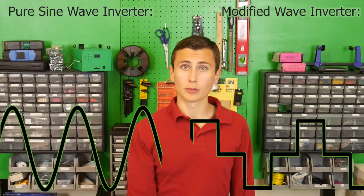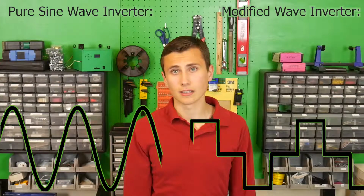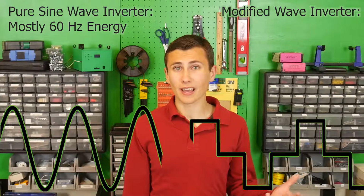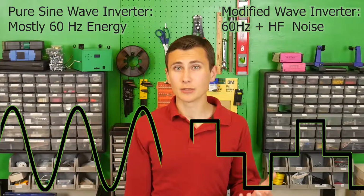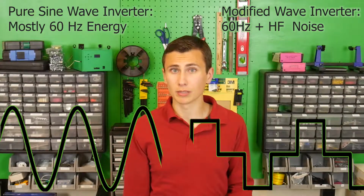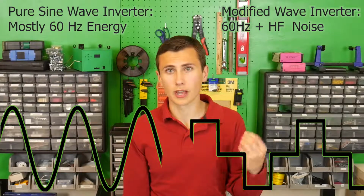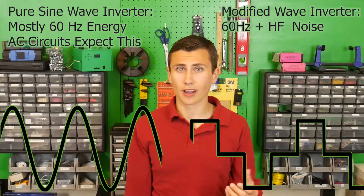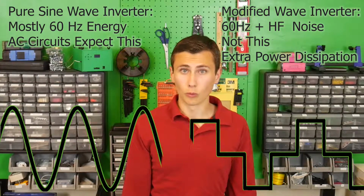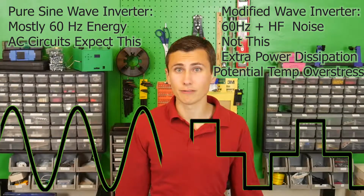The difference between a pure sine wave and modified sine wave input is ultimately that there's energy contained in the power fed to the load at frequencies that your equipment may or may not expect. And this energy needs to be somehow absorbed or diverted by the input power filter of whatever's being plugged into it. That extra energy being absorbed or diverted may cause the electronics to run hotter than normal and may even cause some electronics to fail. At worst, that extra energy may couple through power supplies and cause your electronics to malfunction.